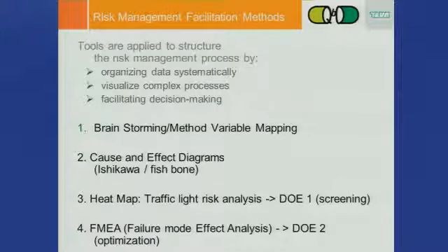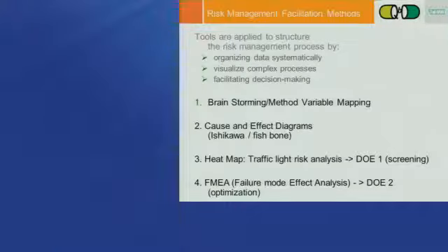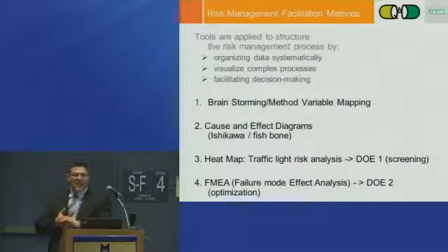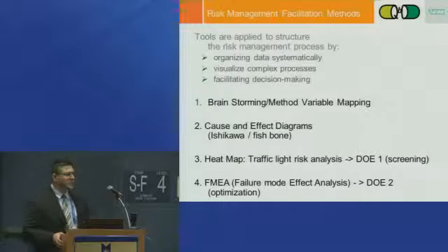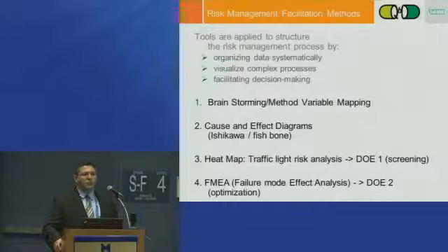After that, you would go ahead and do a DOE 1, I call it, a screening type of DOE. Generally here you might have several variables, 4, 5, 6, and you may not want to do a full factorial DOE, so you do some type of partial factorial DOE or a Plackett-Burman design where using like 11, 12 experiments, you can screen a multitude of variables.